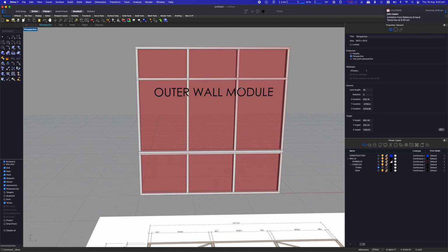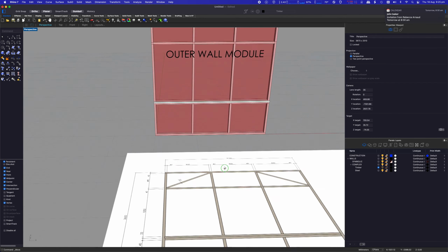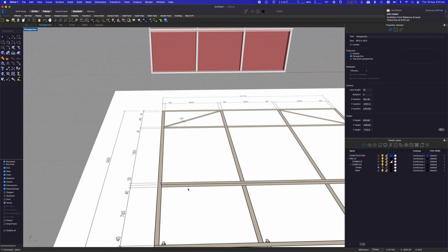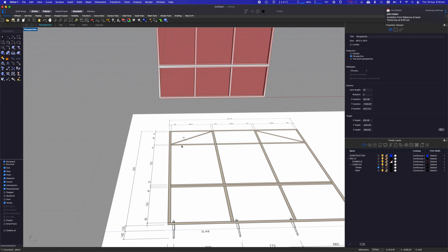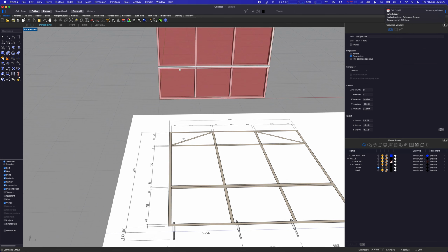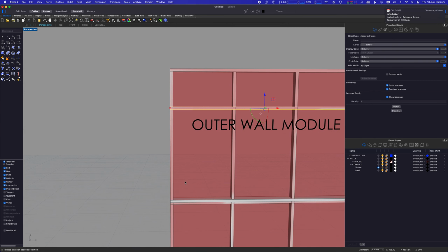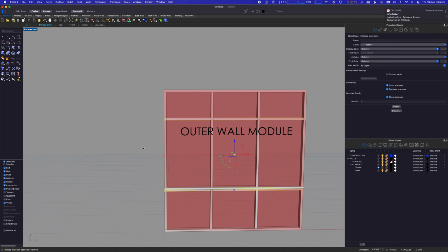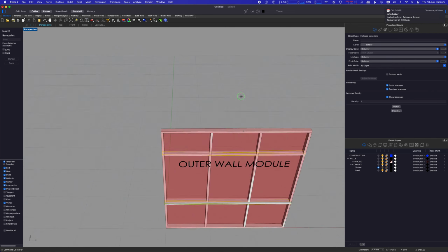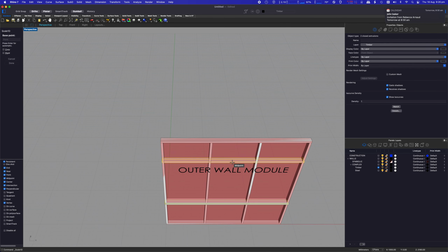So now we can trim a few things up. So you can see that these verticals take precedence. So we will trim those by going, well, I could either Boolean difference them to chop them with these outer bits, but I'm just going to scale them, scale 1D again from their midpoint to the edge.